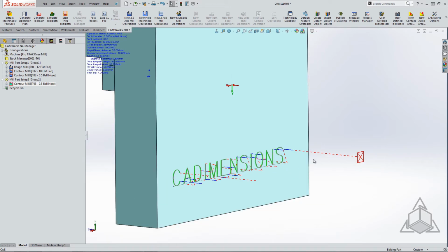But if you're familiar with any sort of other CAM package, you'll know that you might have to cut a pocket into something, and then inside of the actual CAM package, use or try and find the center line or create something. Inside of SOLIDWORKS, you can just go ahead and create these as sketches and then use them after the fact by using that CAMWorks font. Now, if you have to use a stick font, you'll have to resort to the other strategies or methodologies that you had before this one here.